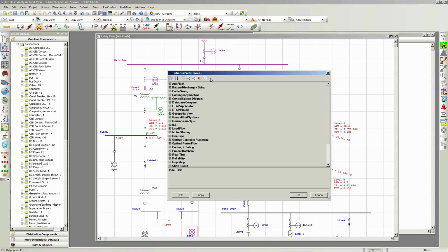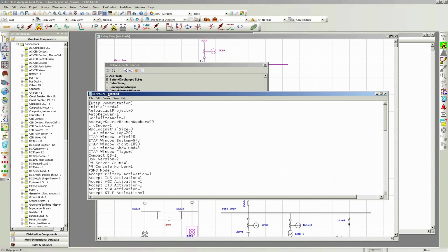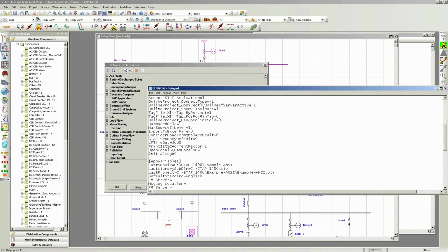It's an advanced feature, this is where you would specify the correction factors. So in order for ETAP to take the orientation factors for the Arc Flash location that is being labeled, number one, you need to specify that at the bus location itself, like I did under the Rating page. Step number two is to go into this etap.s.ini. It's a text file.